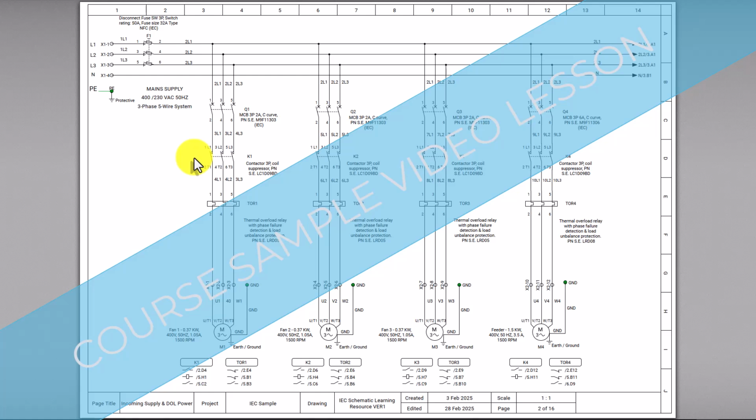I'm on the first page of our schematic set, and I'm looking at a contactor labeled K1. If I go down to the bottom of the page, there is a cross-reference for K1, and it shows that we have contacts at location 2D4, so page 2, D4. So if I go from D to 4, it's referring to these 3 set of contacts. Pretty straightforward for that one.